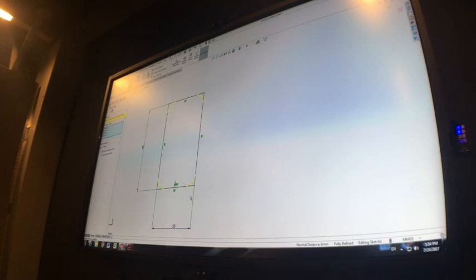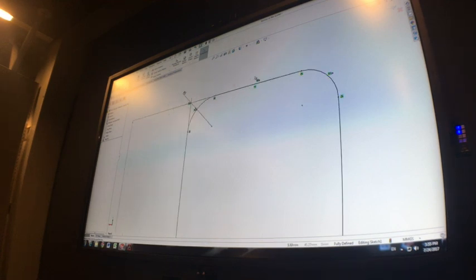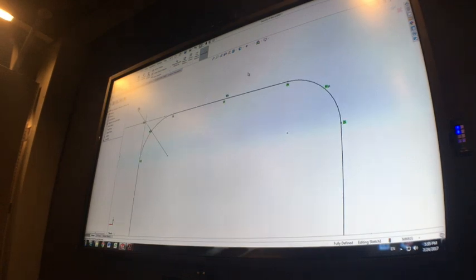And you can see that I'll include those bottom 2 there. Now when we're doing these fillets, we only want to do it to these top 2. So I'm just going to select those and press OK. And that's created those fillets for me. So when it's created those fillets, what it's done is trimmed away the straight line section and added an arc in between. And SolidWorks has added what's called relations for us.